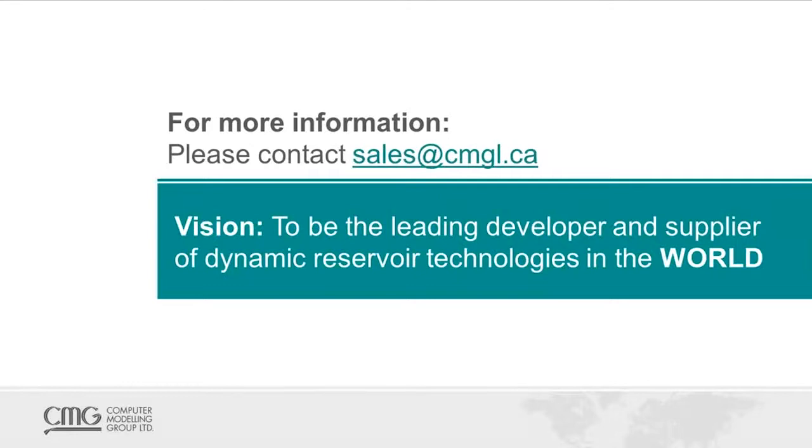The next question is from Mohammed Reza, and the question is, except for the IFT reduction factor, how do we add the direct compositional effect due to interaction of CO2 and reservoir fluid in relative permeability modeling? So actually in GEM you can include the effect of the interfacial tension on the relative permeabilities in different ways. One of the methods is to directly define the relative permeability curve as a function of interfacial tension.